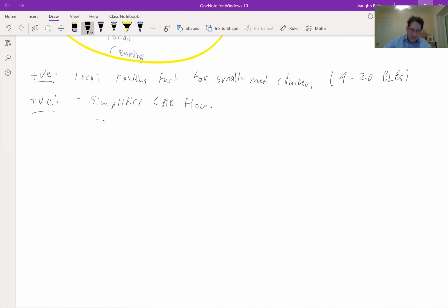Basically, we can do a CAD step called clustering. We don't have to do this, but we now have the option to do this. Clustering is basically a bottom-up partitioning. I talked about partitioning, and partitioning CAD tools tend to be quite good. Partitioning tools take a big blob of logic and cut it in half. And then you might cut the halves in halves and so on. Clustering is really the same problem, but you attack it with a different algorithm.